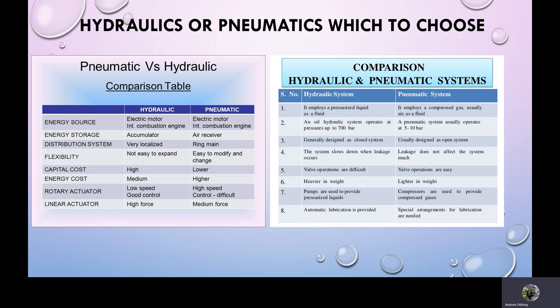The result of that is if I have a leakage in my pneumatic system, it doesn't affect the system as much as a hydraulic system leak, which can be catastrophic, as well as very dangerous. Air leaking out at high pressure, other than getting whipped, it's probably not as bad as if a hydraulic hose lets go. That would be much more egregious.